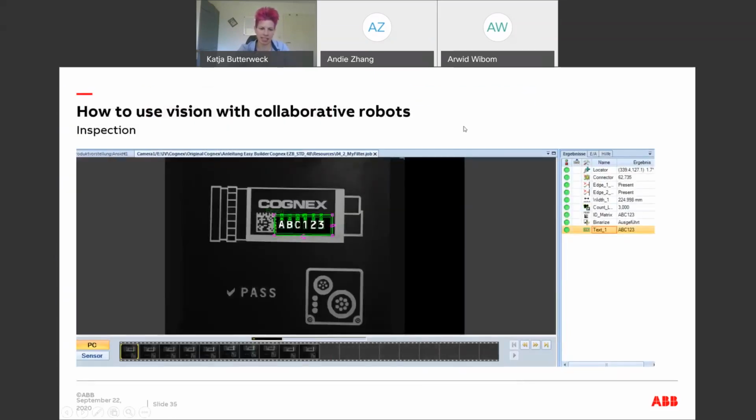For reading text, there's also one recommendation. There are filters included. And if you put a filter on top, for example, here to increase the contrast, it's often a lot easier to read some text. So here, for example, we have the binary filter on top, and then it's a lot easier to put one more vision detection on top.